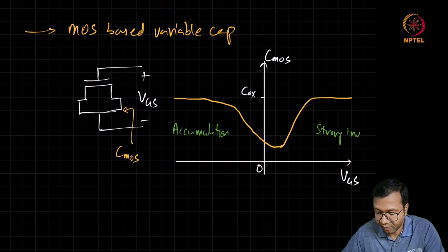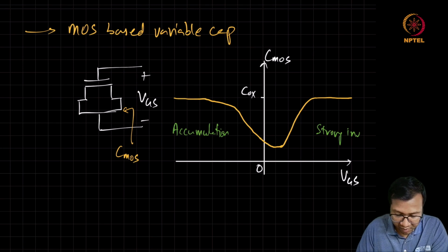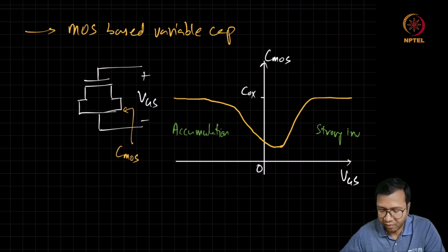As a result, we are going to get a non-monotonic CV characteristic using a regular MOSFET, which is not desirable, especially when we are using a VCO in some kind of feedback system where we are trying to set a specific frequency by controlling the VGS. This kind of non-monotonic behavior can make such feedback systems unstable.